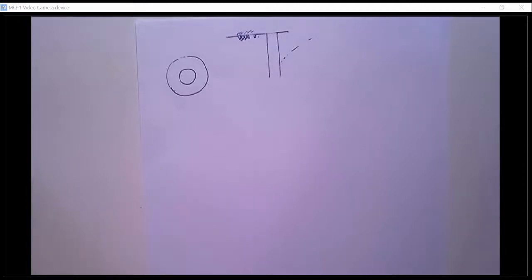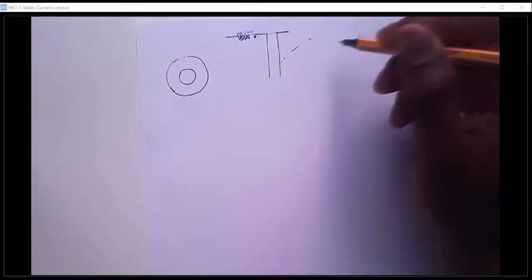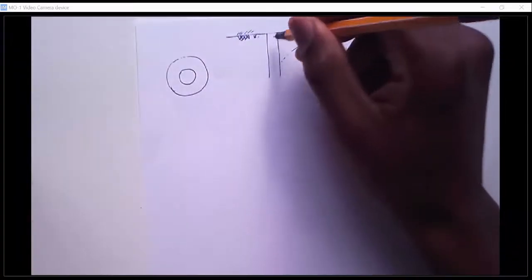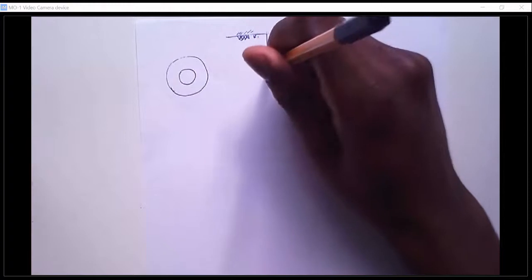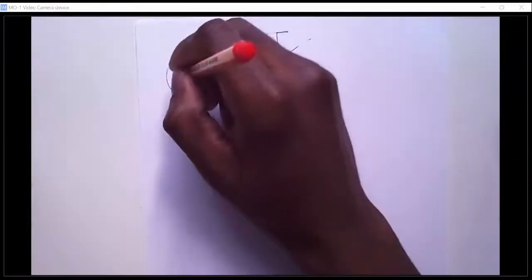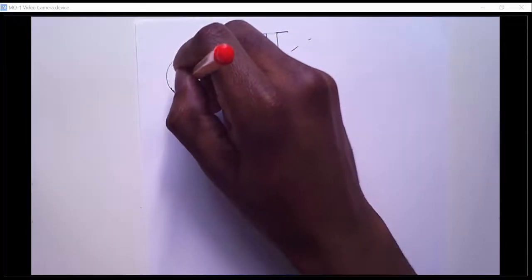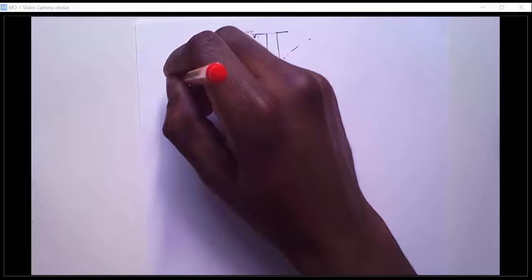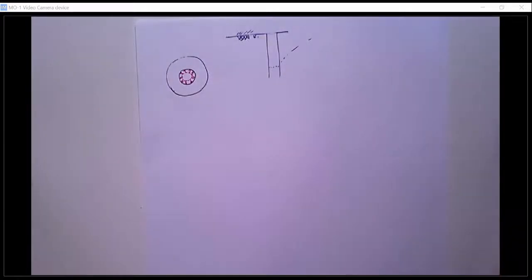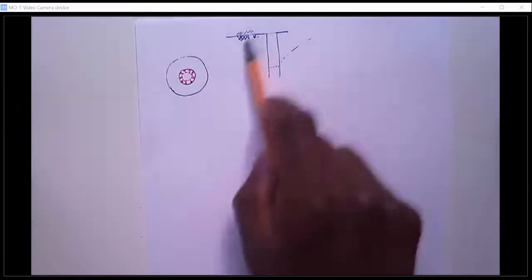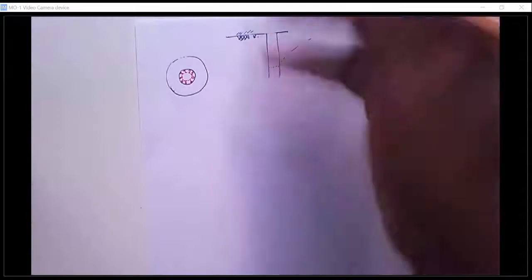We can use it to reduce the level of water, maybe, or just to figure out what the level of water in the ground here is. So it's a well. When you have something like that, at some point you're going to have water inside, and we could say that the water is exerting some pressure on the inner boundary, in the radial direction, and we want to figure out what happens. The disk here, the medium itself, could be the earth that's around the well.